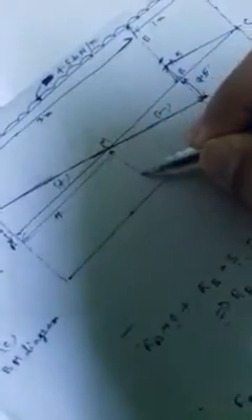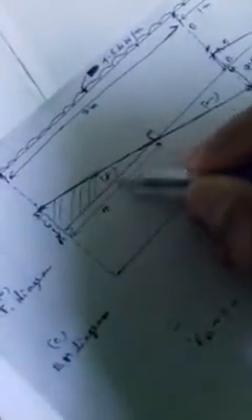This will also be an inclined straight line because it is UDL due to the rule, but here the SF diagram changes from positive to negative at this point. Let the point be M, and the distance from A to M is X. So similarly, take one baseline for the SF diagram and one baseline for the BM diagram, and add this point. So this is the SF diagram, and this part is also positive.